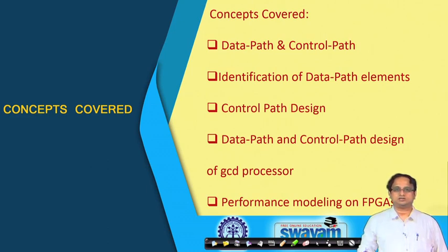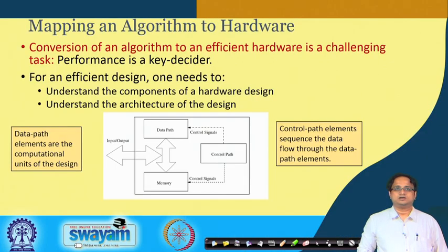How you design is one aspect, but how do you also explore various opportunities and implications of your design? How do you analyze the scalability of your design? We will be considering FPGAs with k-input LUTs. In this case I will be taking k equal to 4, and we will try to model the design and understand how the performance scales.